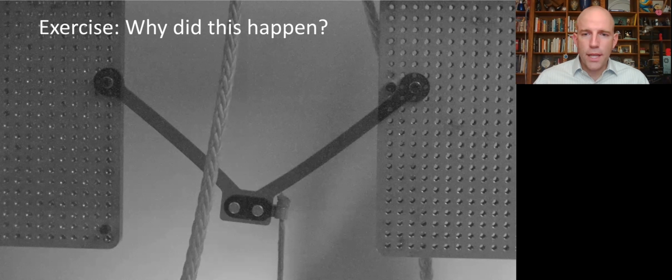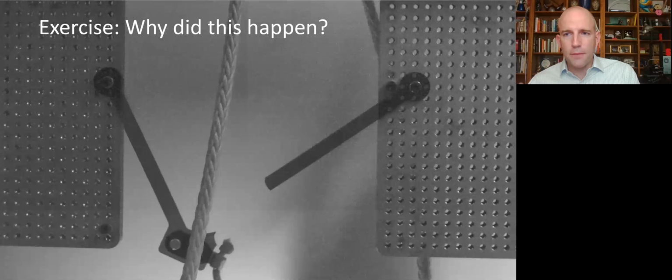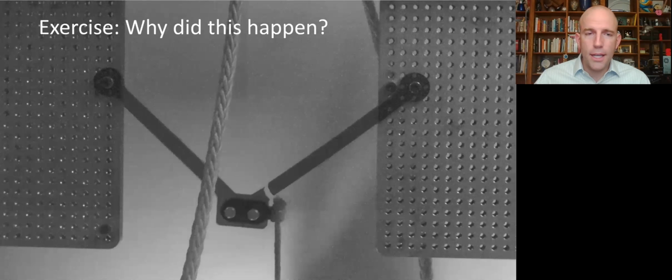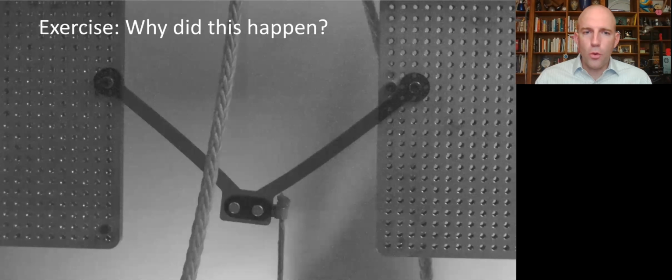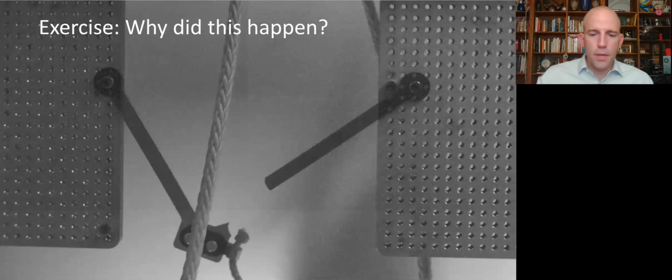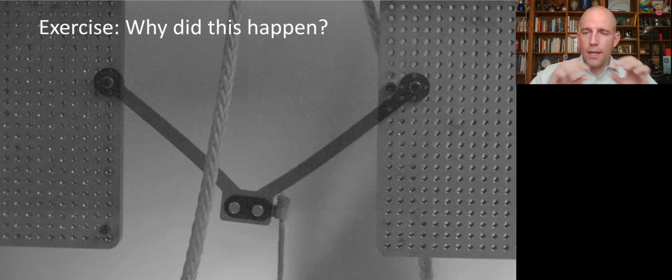And as we do these things, we'd like to try to leverage the terminology and logic and engineering models we've been developing in our mechanics courses and in this design course. So the way I like to think about what's happening in this part is considering the deformation first, because that's the most obvious to me. And you can see that these arms are bending upwards. This one's bending sort of up, and this one's bending down. And wherever you have a bent shape, then you have bending loading, right?